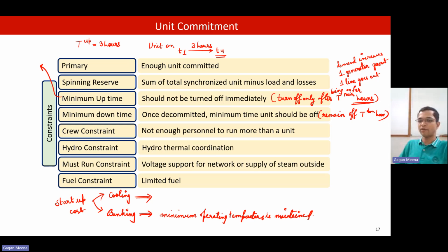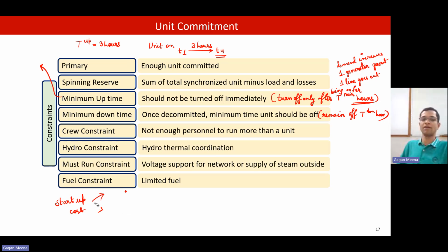So to bring the unit back from banking will require less time, fewer hours. And after completely cooling, it will require a long time, several hours. And that's why it's time dependent. Startup cost is time dependent. It is not time independent. It depends on how many hours ago the unit was off.